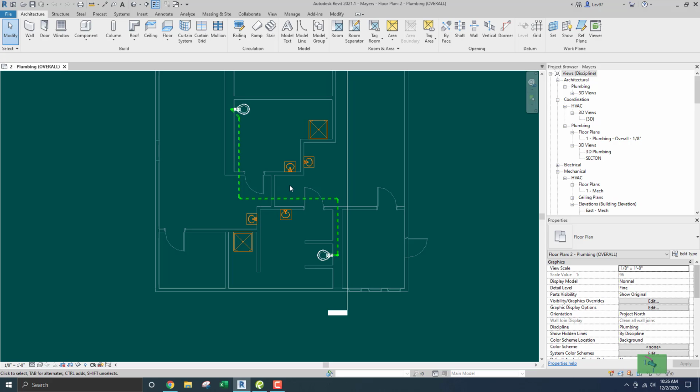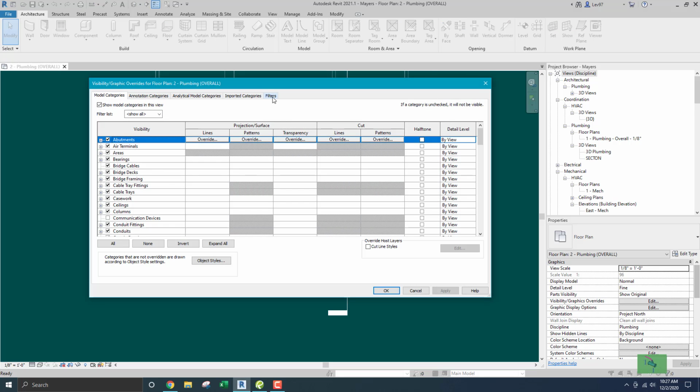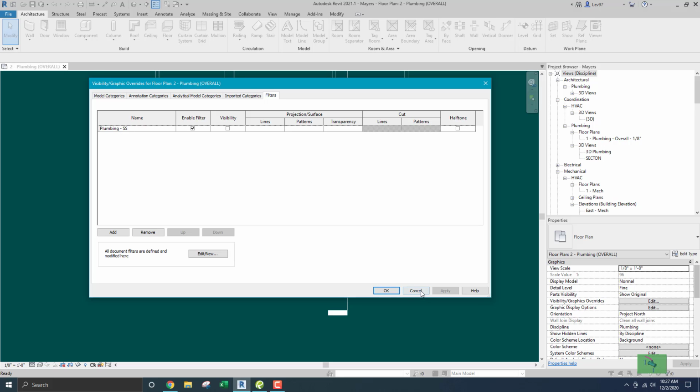So if you just have, like, from your shower, your lavatories, your sinks, and then if it's from a kitchen, it would be called grease waste, or GW, right? Or acid waste, AW, if it's from a laboratory that carries acid. So there's different kinds of abbreviations that we use in the industry. So that's why that is plumbing, SS, sanitary soil.